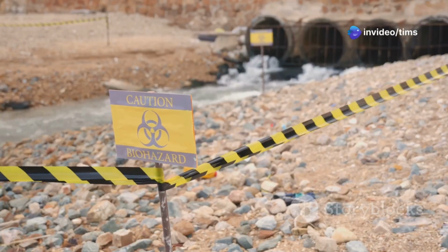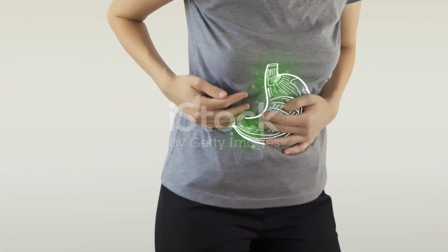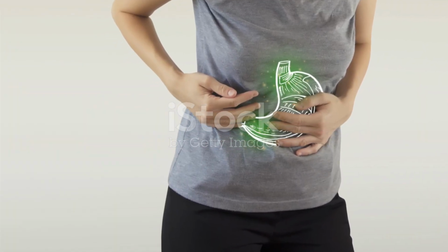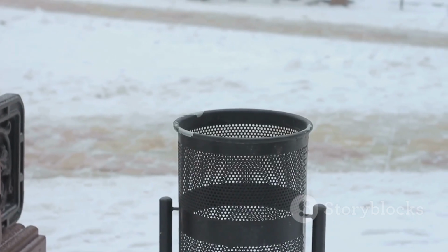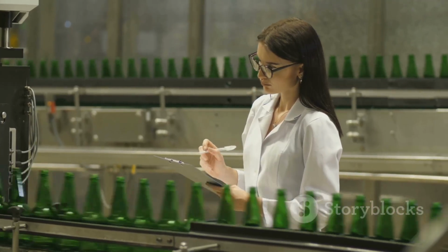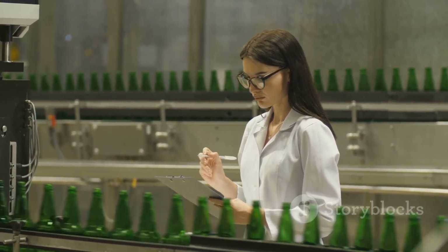More importantly, droop can allow harmful bacteria to contaminate the food. This contamination can have serious health consequences for consumers. Consuming food from a can with a droop defect can lead to food poisoning. Regular inspections of double seams and proper maintenance of seaming machines are essential to prevent these risks.